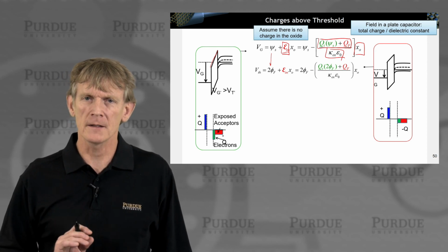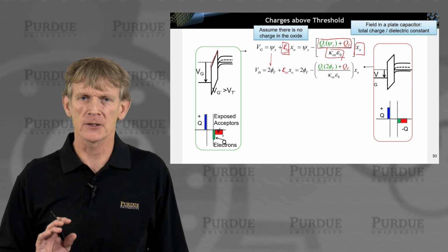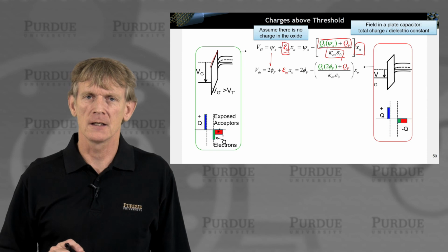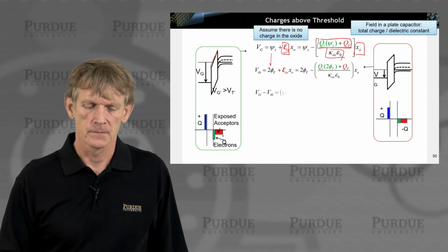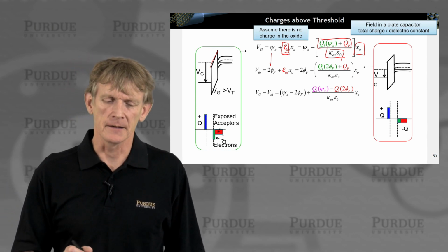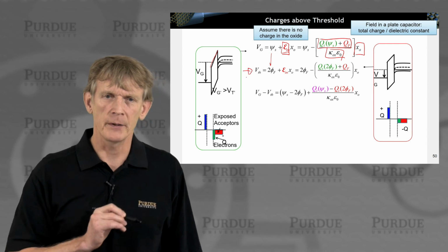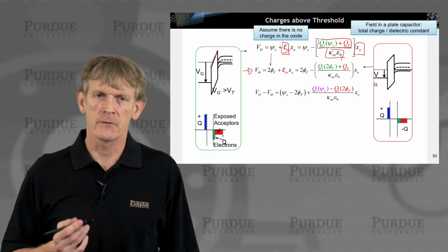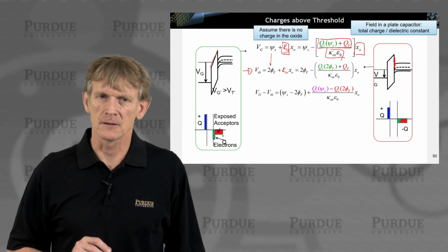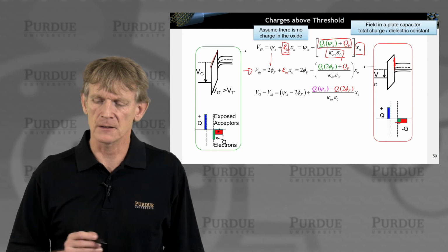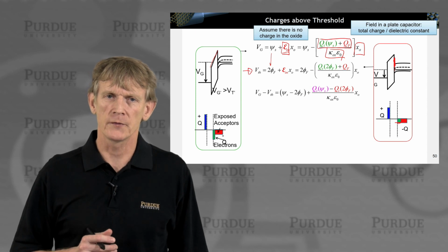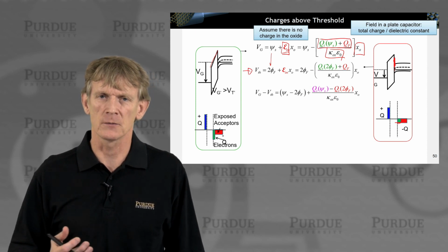Just follow me. All we're doing is defining threshold, when we want to build a difference between the gate voltage and the threshold voltage. So we're going to build a difference here between those two voltages. Again, threshold voltage means we're just about to turn on all the inversion charges that will pile up here at the interface. So at threshold it's just the same as the acceptor doping. Now we're beginning to pile this up, and we define that voltage as that transition point.